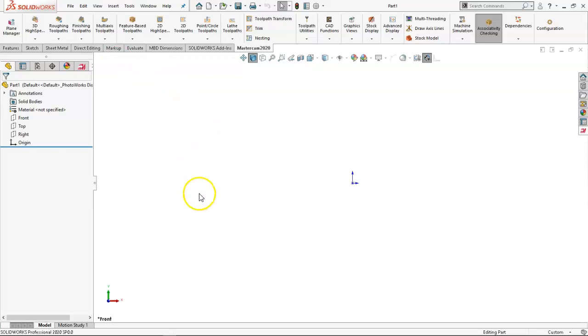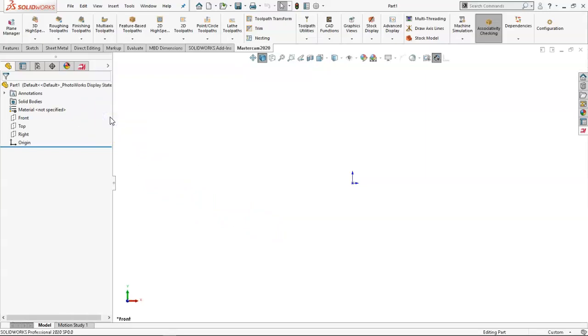And in some ISO documentation control systems, I technically cannot change that original document without it going through a revision process. If I add a line and say, oh yeah, I'm just going to tell my face mill to follow that line, no, you can't do that. It has to go through revision, and you change the document. So in order to combat some of those things, taking an assembly creates a completely separate document, a manufacturing document that is controlled under a separate set of rules. So it's one of the considerations.